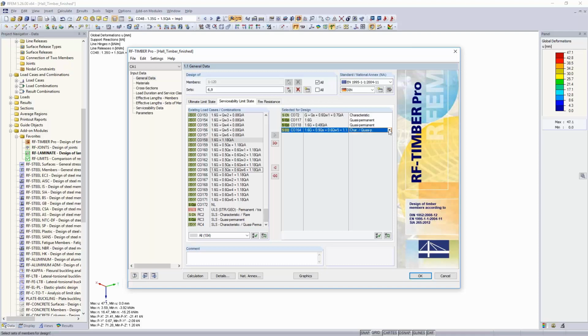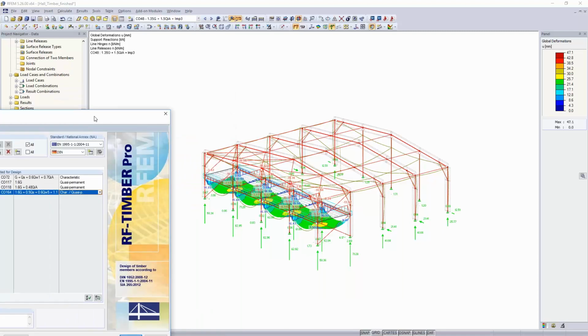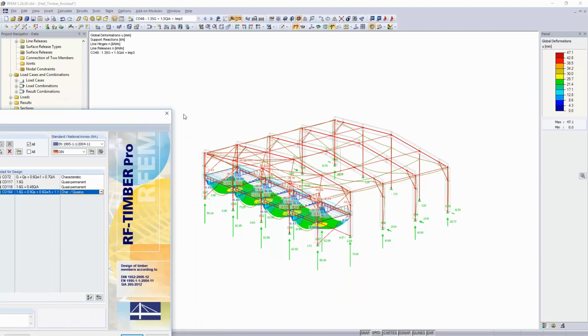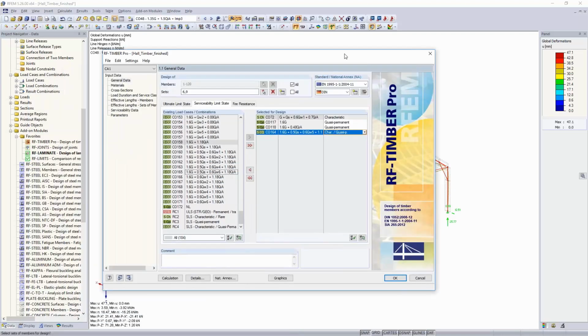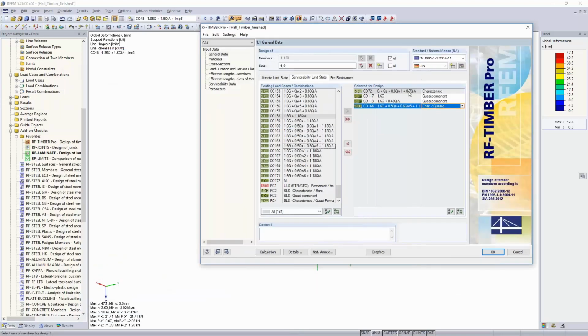Okay, once again, it's similar to what we have had in the laminate add-on. It's automatically designed. If you want to do a simplified vibration design, you could do that here as well. But for the members, I don't see that too problematic here. Maybe for the CLT, as I said, that would be something I would maybe do or add, but we're not going to do that today. Fire resistance is possible with Timber Pro. It is also possible with the laminate add-on, but it requires more effort. Maybe Gerhard or I will send you an FAQ where we answer that. So it's possible, but in laminate, as laminate generates stiffness, it is just more effort to do.